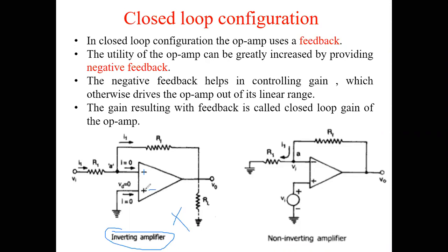If you simply interchange the plus and minus and do not apply the input as per the concept, the entire concept is wrong and whatever you have written will be wrong. So be very careful with plus and minus. Since it is an inverting amplifier, the input is given to the inverting terminal.